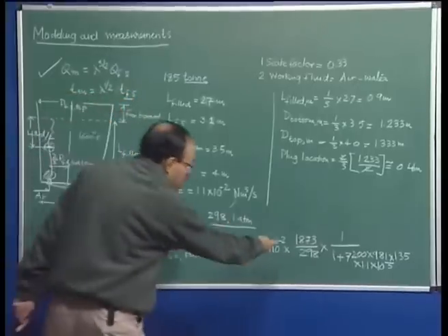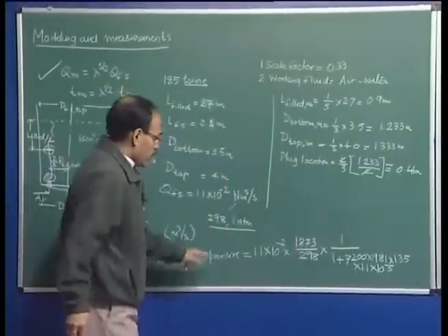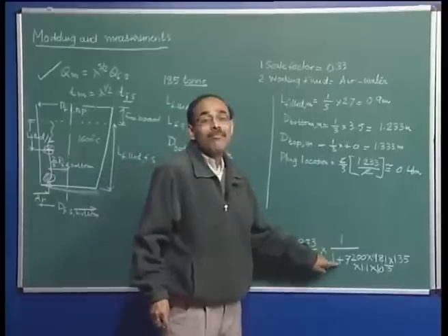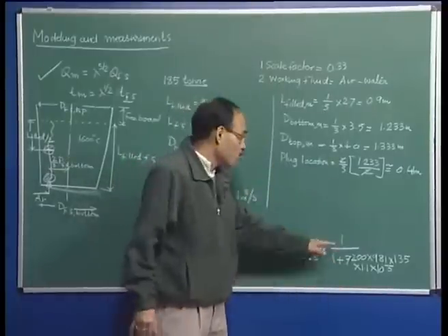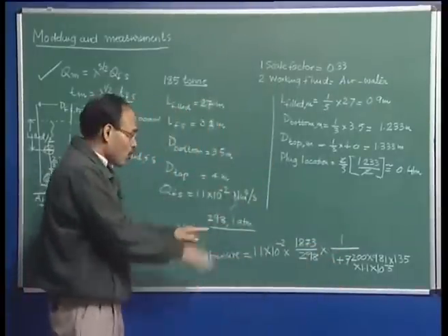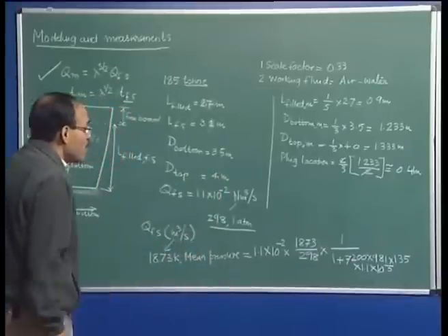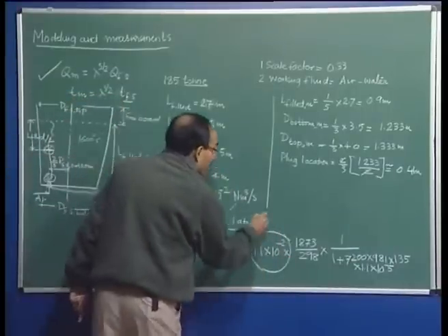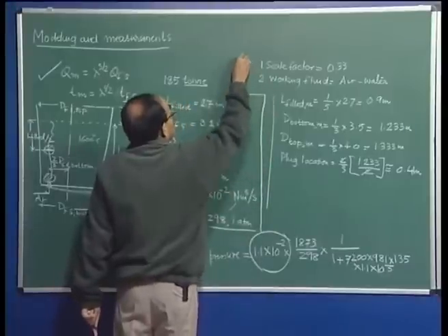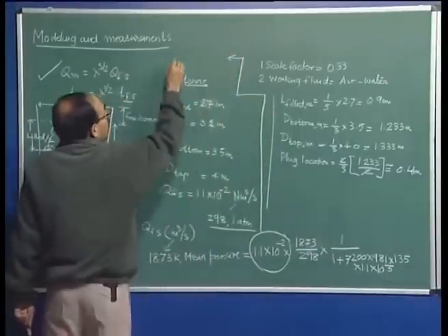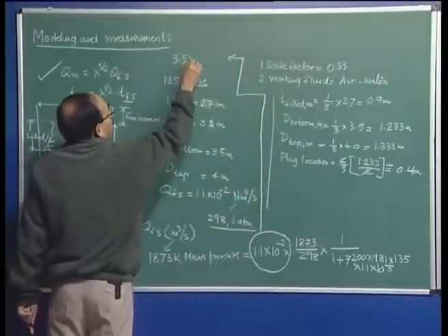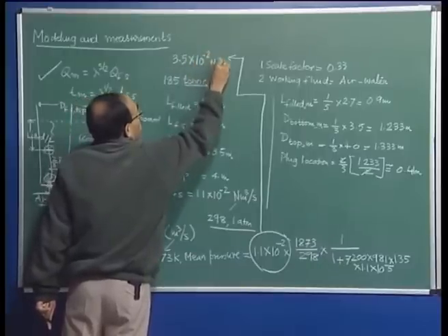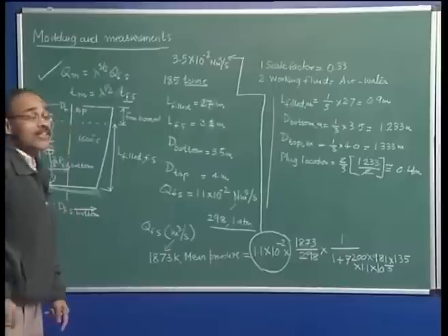So, because of this component, the gas volume is going to be increased by a factor of 6. Because of this component, it is going to be decreased by a factor of 2. So, the overall contribution of pressure and temperature is going to be, this gas flow rate will feel like approximately 3.5 times that is the gas flow rate.